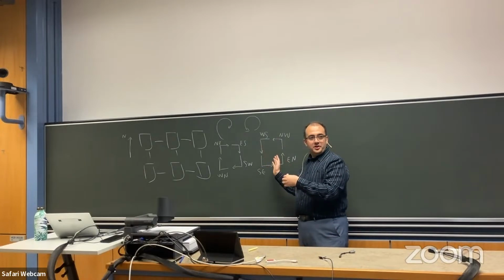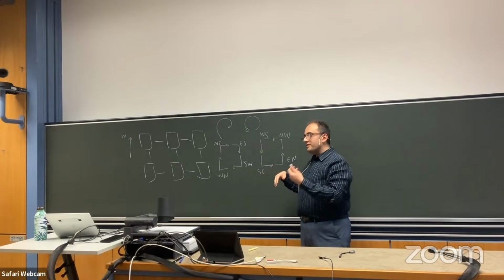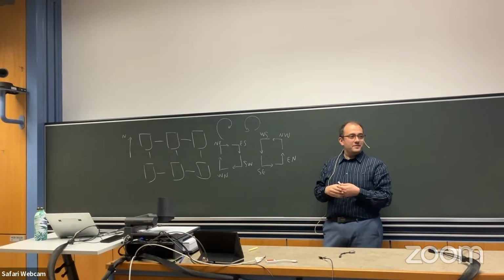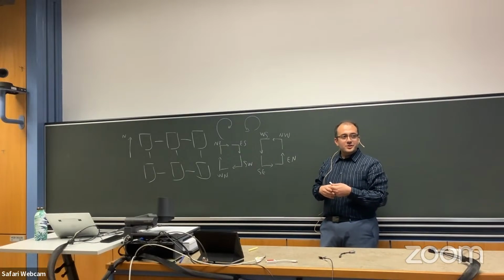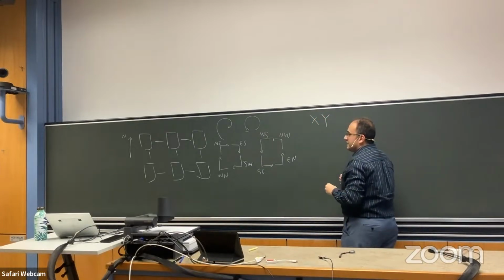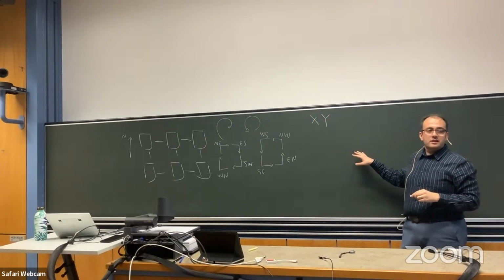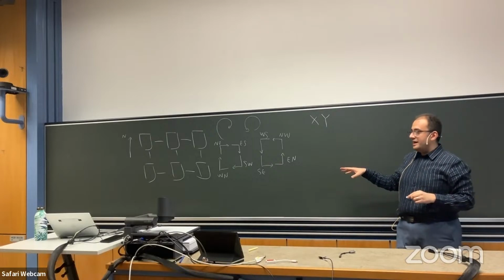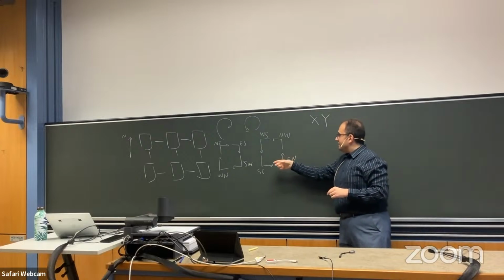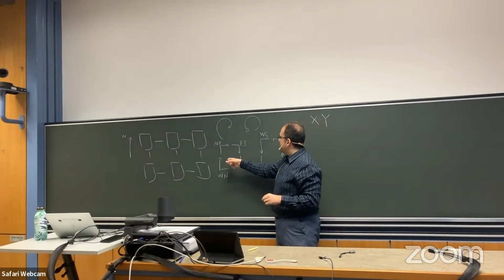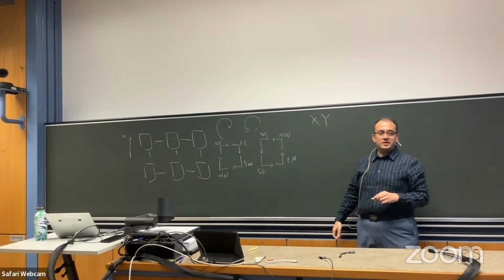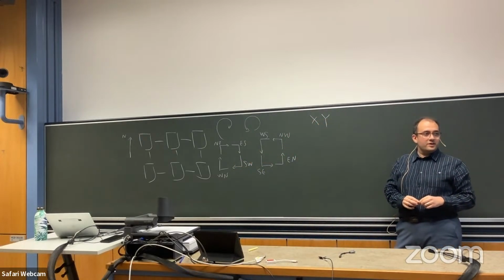Now, if you let your routing take all these turns, you can get circular dependencies. One way to break these circular dependencies is to restrict some of these turns. So let's start with XY routing. With XY routing, we know that XY is deterministic, and you always need to take X and then Y. Can you tell me which turns we are omitting in clockwise and which turns we are omitting in counterclockwise with XY routing?